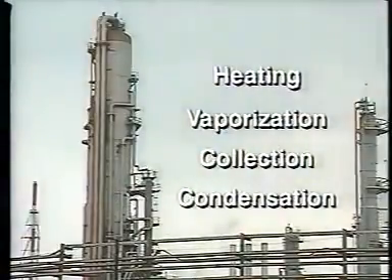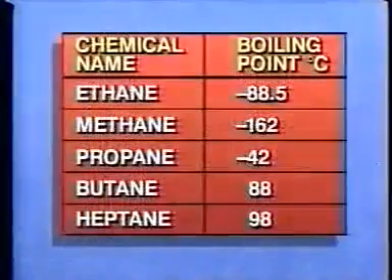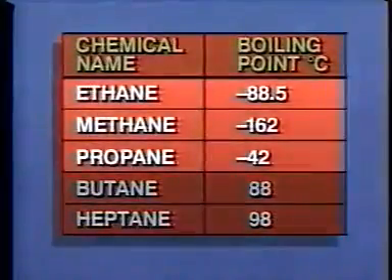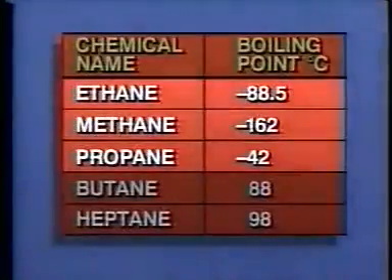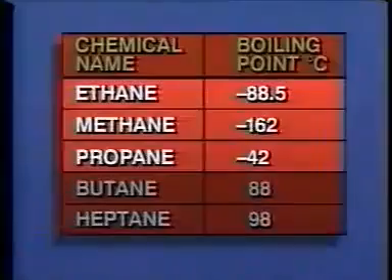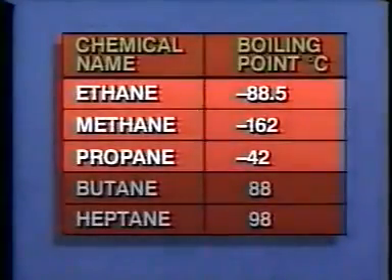This is also known as distillation. Because many components have extremely high boiling points, low pressure is used to drive boiling points down. Other compounds, or fractions as they are called, have very low boiling points. Most often, these are gases, and high pressure is used to condense or liquefy them. These liquefied hydrocarbons are more easily stored and transported.